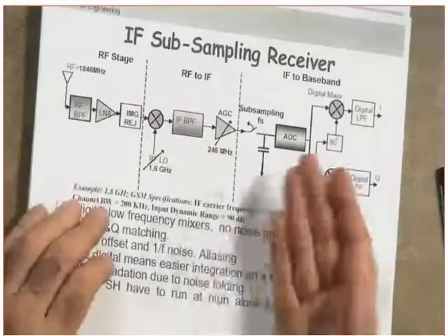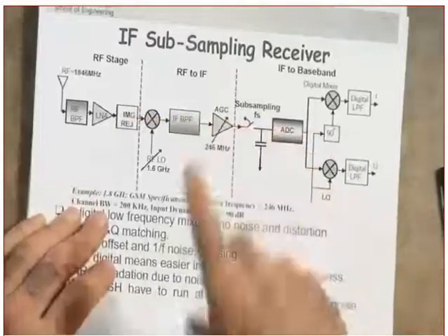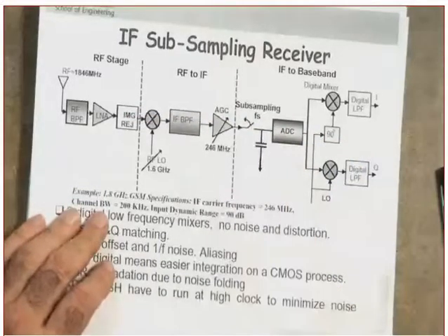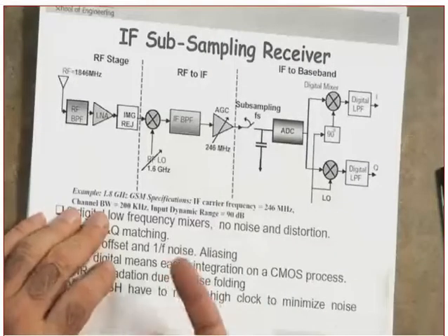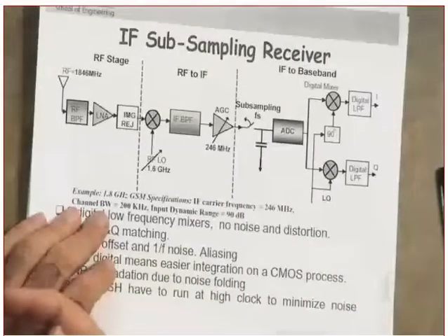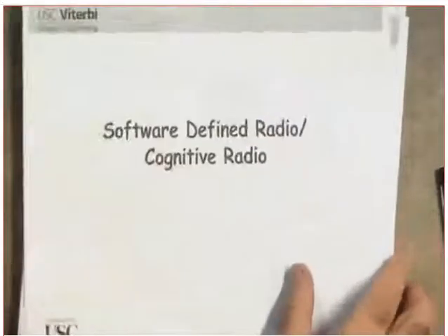The problem, again, as I told you, I will show you that in just a second. The problem is that as you move this way, the carrier frequency will become what? Will become higher, which means what? The sampler needs to work much faster. Are you following me or not? The resolution of the ADC requires what? Much higher. Clear? Okay, good. Now, this I will assign for homework.